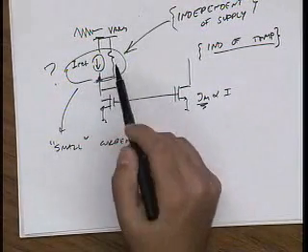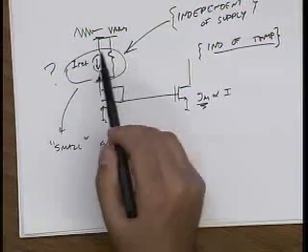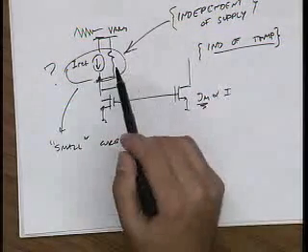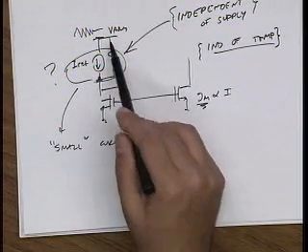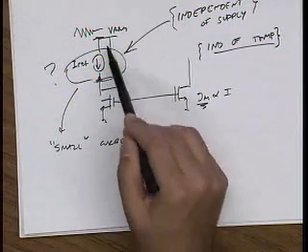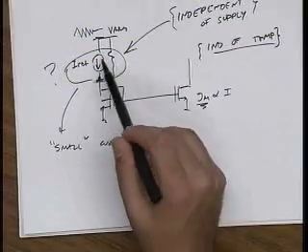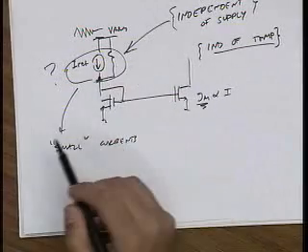Well, sure, but that resistor is going to vary plus or minus 10%, right? That's one issue. Another issue is that big resistors are a bad idea on chip. They take up a lot of area. So there's got to be a better way of generating very small currents.